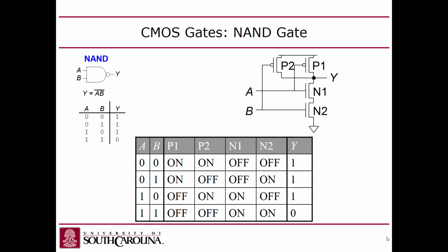So you want to build your pull down network like that. So A and B would be, if you have A and B, if they're both 1, you have A and B, and then there would be ground right there, right? And this would be your output. Right? Or you can have, alternatively, either one of these implicants here, these not A, not B, or C.